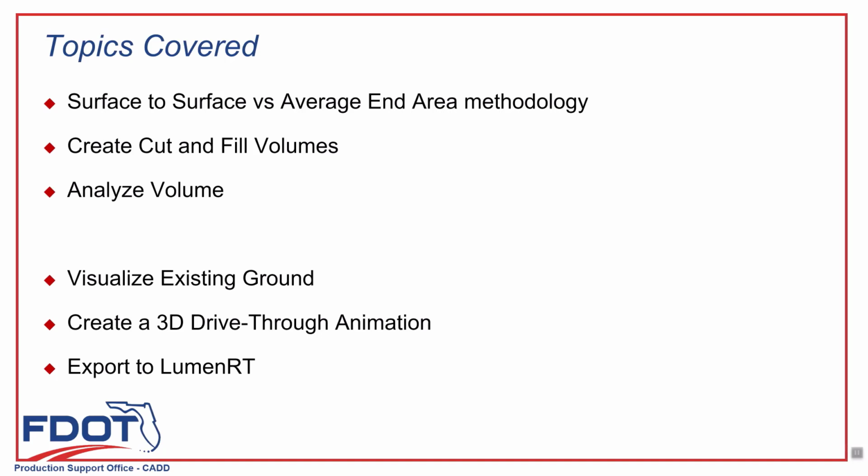Then we're going to go into visualization. We'll show you how you can visualize the existing ground with more than just DTM. You can actually pull in aerials. We'll do a 3D drive-through animation, and we'll also show you how to export to LumenRT, which opens up a whole lot of options. You can view it in 3D with the textures on a screen, or you can even put it on Oculus Rift or some other virtual reality headset and view it there and literally walk through your project as if you were doing a site visit for your proposed project and check to see what issues you have with your model that need fixed.